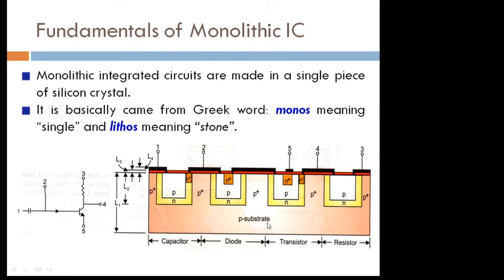सबस्ट्रेट। तो जिस पे आप डिफरेंट डिफरेंट कंपोनेंट फैब्रिकेट करने वाले हो, वो बेसिक चिप को हम सबस्ट्रेट बोलते हैं। ऑन एन एवरेज इट्स ऑलवेज अ पी टाइप मटेरियल, तो हमने यहाँ पे लिखा है पी सबस्ट्रेट। ठीक है, फिर से आईसी जिस पे बनती होती है वो बेसिक चिप को सबस्ट्रेट बोलते हैं। और सबस्ट्रेट इज़ वेरी वेरी लाइटली पी टाइप डोप, माने ट्राईवेलेंट इम्प्योरिटी ऐड करेंगे, माने एल्यूमिनियम ऐड करेंगे या तो गैलियम ऐड करेंगे, जिसकी वैलेंसी 3 होगी तो एक होल जनरेट होगा, और होल पॉजिटिव है तो पी टाइप सबस्ट्रेट